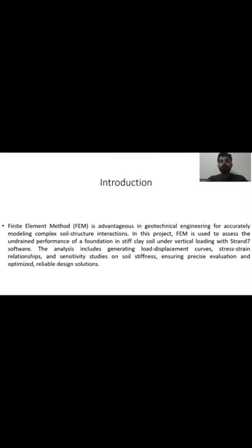In the introduction, the finite element method is very important in geotechnical solutions for accurately modeling complex soil-structure interactions. In this project, we are using the finite element method to assess the undrained performance of foundations in stiff clay soil under vertical loading, with Strand 7 as the software. The analyses include generating load displacement curves, stress strain relationships, and sensitivity studies on soil stiffness,